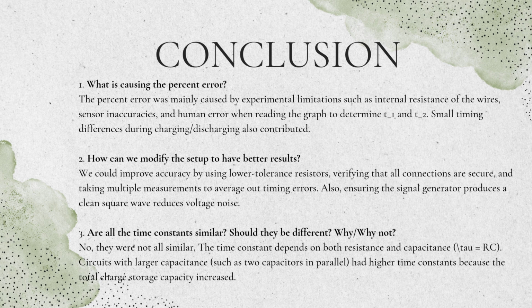We noticed that the time constants were not similar, and it depends on both the resistance and capacitance. Circuits with larger capacitance, such as the two capacitors in parallel, had a higher time constant because the total charge storage capacity increased.